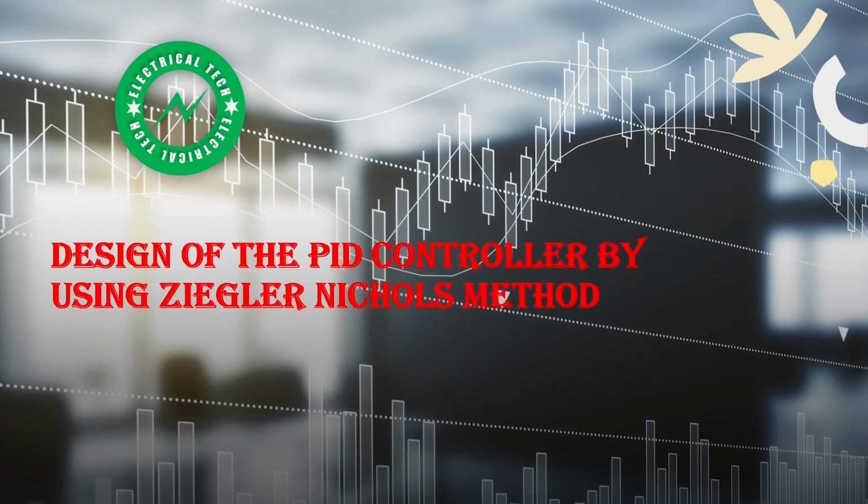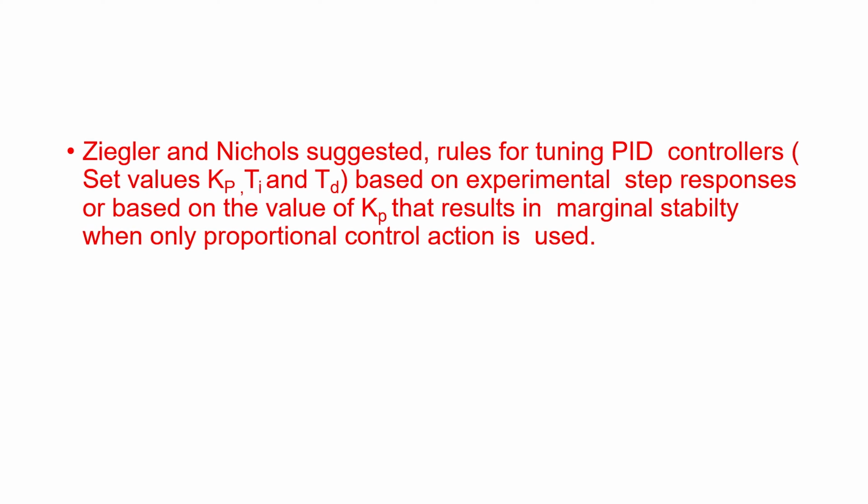Designing of the PID controller by using the Ziegler-Nichols method. Ziegler-Nichols suggests the rule for tuning the PID controller. We need to set the value for Kp, Ti and Td based on our experimental step response, or based on the value of Kp that results in the marginal stability when only the proportional controller action is used.